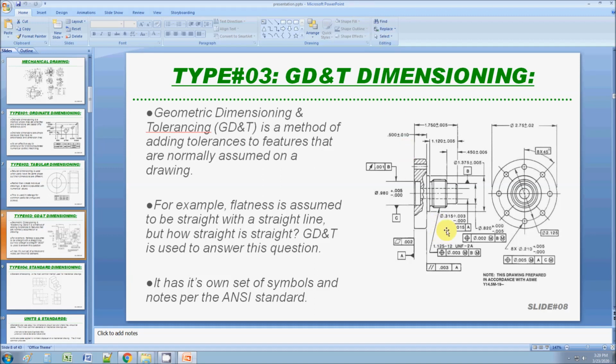First of all, not every machinist is familiar with GD&T symbols. Second of all, whenever you spec something like this, a lot of times you have to design custom gauges to control this. This is not a simple specification. Okay, you're putting references on datums with certain tolerances. You need to design a special fixture just to test this. So this is mainly used in high volume manufacturing products.